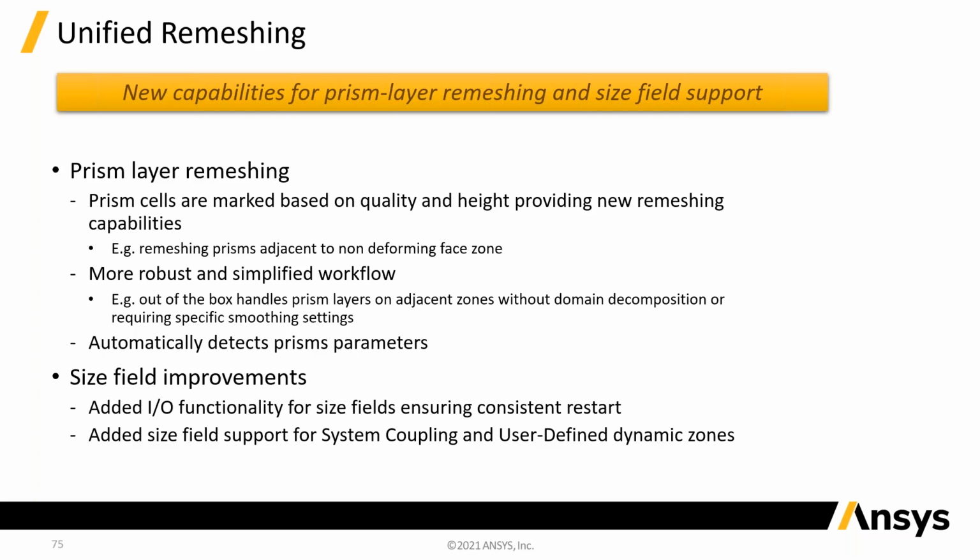What this size field improvement does is allow the code to capture the size fields around an object and move them with the object, so that the good quality mesh around the object just moves with it. So that is a really good improvement there. Obviously, this needs to move to polyhedral and it's ongoing work, but there's some really significant improvements if you're using TET and prism meshes.